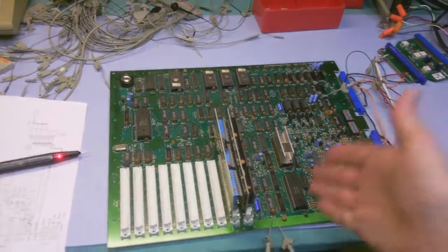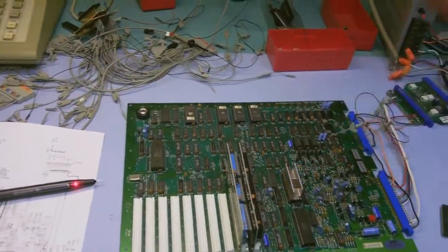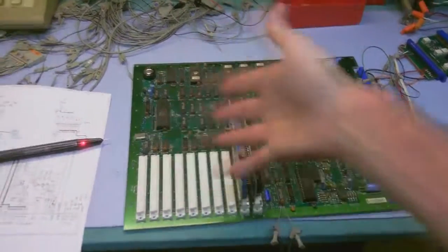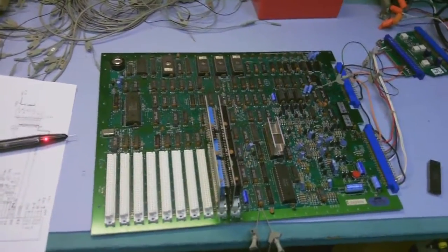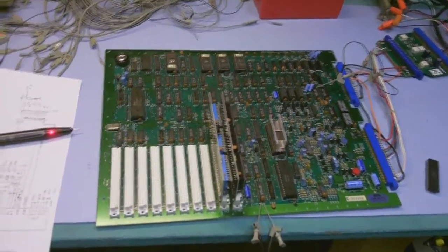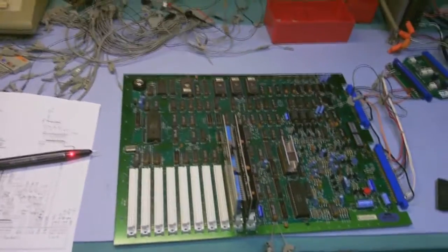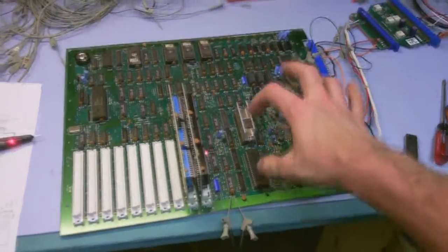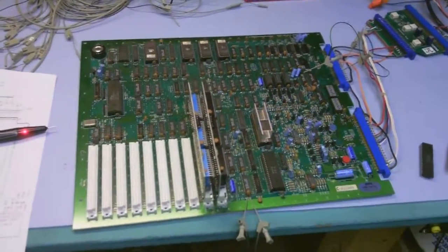And anyway, so that's what happens. The Z80 controls the menu. When you choose your game, it kicks this guy off, and he in turn will start reading the ROMs based on the game you select. So that kind of narrows it down. I mean, we're getting a menu, and those kind of things are getting displayed properly. But the game itself is not playing, and so I'm guessing it's got to have something to do with either this guy itself or the controls to that guy.